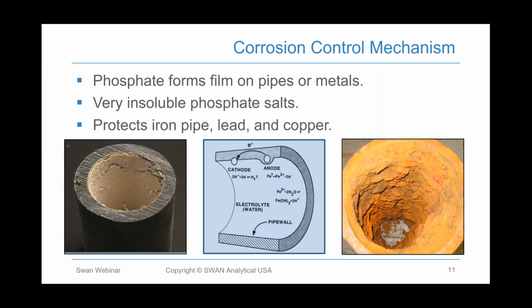And actually inside our pipe, our water is acting as the electrolyte. Like a pH probe, we may have a refillable pH probe where you're putting KCl inside a probe as a conductor. Water is actually our electrolyte in this case. So it's both making our end product and making things worse all the time. So that's how that functions inside.